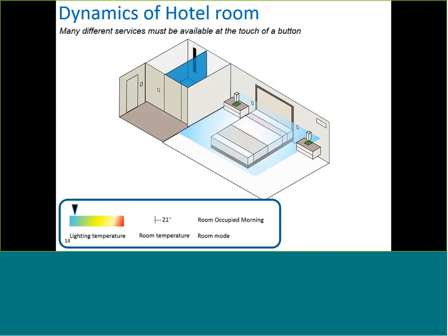As we move into the afternoon, we'll change the cove lighting to a warmer colour, and then in the evening, we'll go warmer again. The advantage that we have with the network lighting control system is the automated response of the colour temperature. So rather than having multiple buttons which the end user would have to navigate through, we will simply present a simple on button, and then the time-dependent response will come on as requested. This simplifies the user interfaces within the room, making it much simpler to drive the different features within the room.